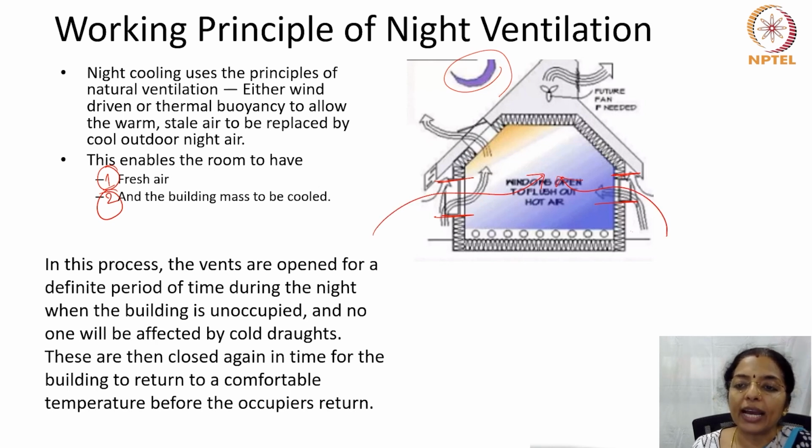The cool air which enters the building lowers the temperature of the indoor air, and that is absorbed by the internal surfaces, and as I have already been telling, warm air rises up and escapes and cool air is retained. And during the day, this must be closed. All the vents must be closed so that the cool air is trapped inside.